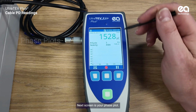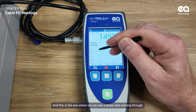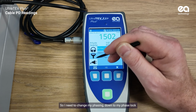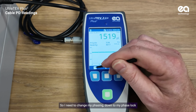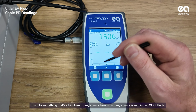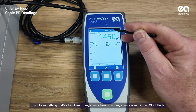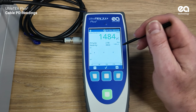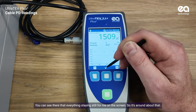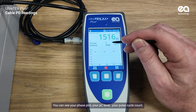Next screen is your phase plot one. This is the one we use most of the time, and this is the one where we can see our phase plot coming through. So I need to change my phase lock down to something a bit closer to my source here, which is running at 49.73 odd hertz. Yeah, you can see there that everything's staying still for me on the screen. So it's around about that. You can see your phase plot, your picocoulomb level, your pulse per cycle count.